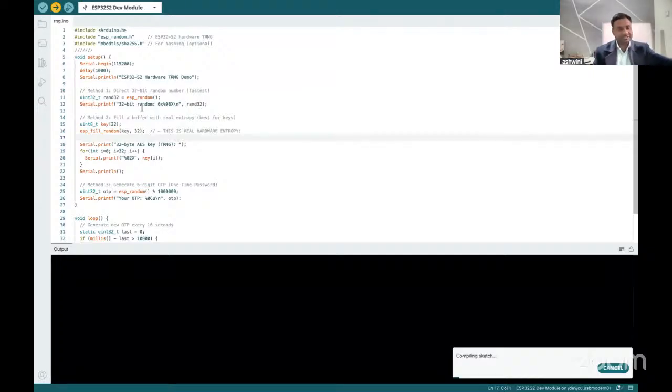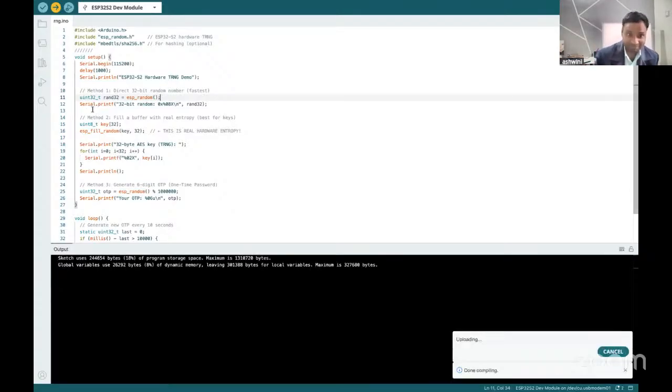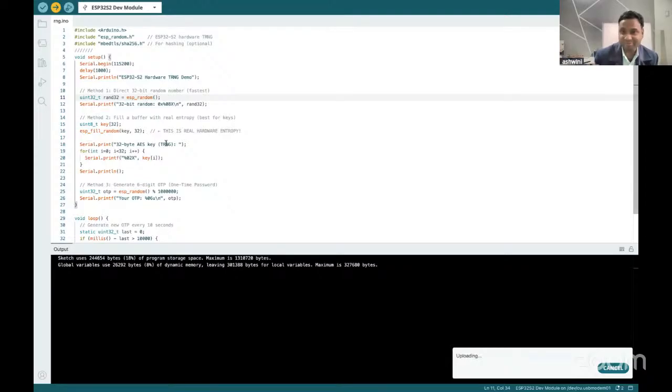So what this code will do is use this library, and within this library it will automatically run this ESP random function, create the random number using the integrated chip inside the board, and output the random number to you. Or else, if you have given the fill-in-the-blanks for that, then it will fill out the random number with your generated random number, like 1 2 dash dash 1 3 4. So in between the dashes, it will print its own random number. Okay. So I am uploading the code. Now it will output the random number generated by the chip inside the board.